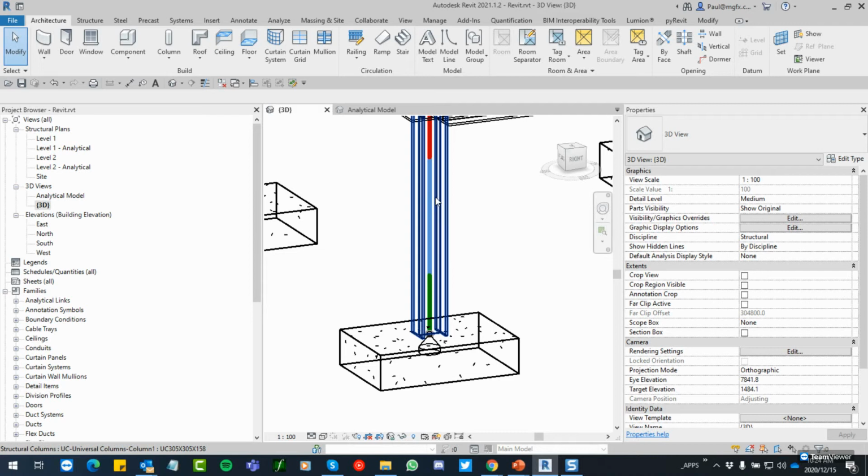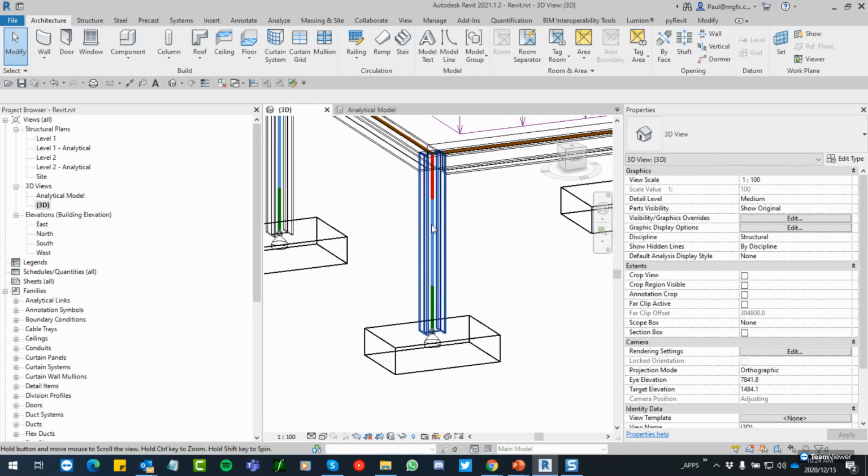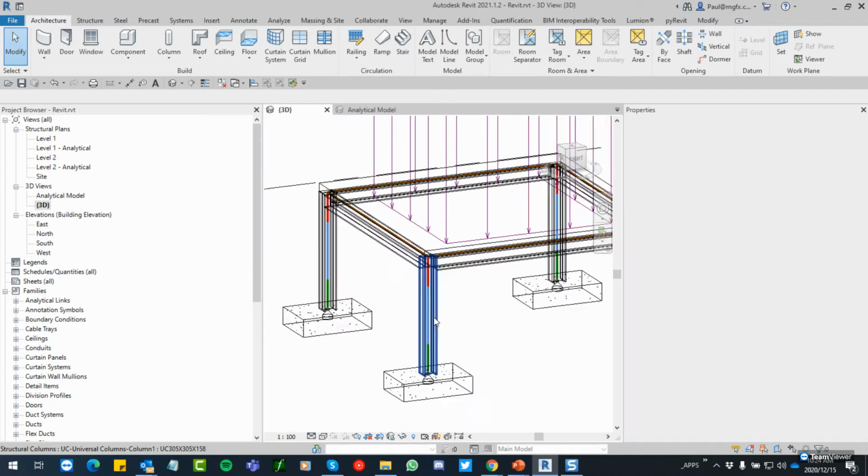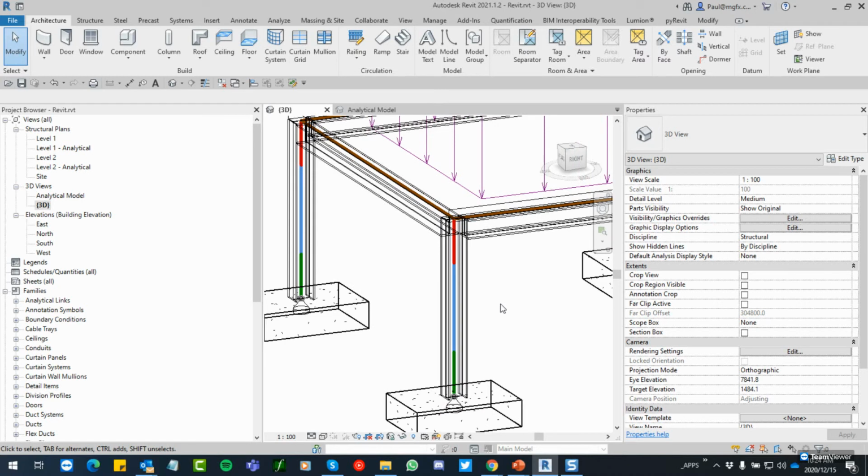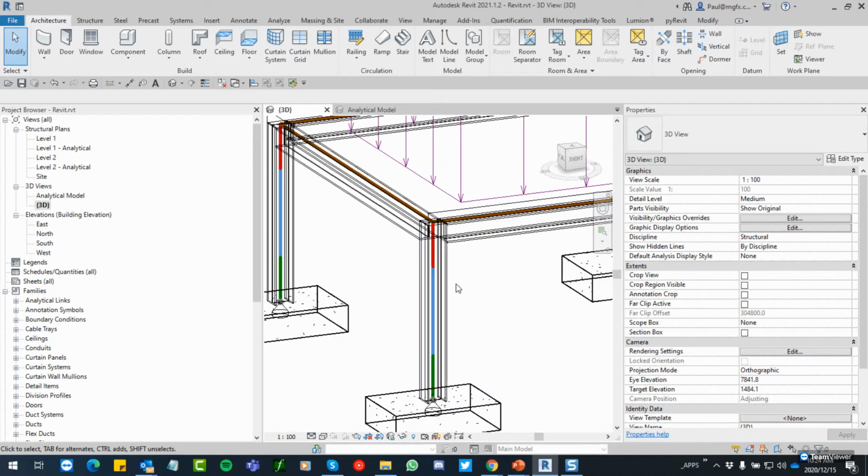In classical theory, we would expect this to be the neutral axis, but it isn't. You can offset the physical element from that analytical model, and so it will be an engineering approximation to some degree, within 5 or 10% or whatever. If you find that the results don't make sense to you, you might have to adjust the analytical model to represent the physical model more closely. But if you work with a factor of safety and within the building code, it should be okay.